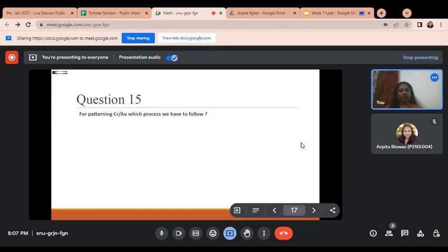The upper layer is gold, and below it is chromium. So we use the gold etchant, and then we use the chromium etchant. So this is the process. In between there is a hard bake process after the development, which is 120 degrees centigrade for 1 minute, and after the etching we can see that the pattern is transferred on the chromium gold. So this is the photolithography stage which we use for patterning the chromium gold.